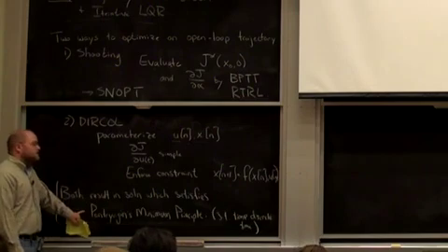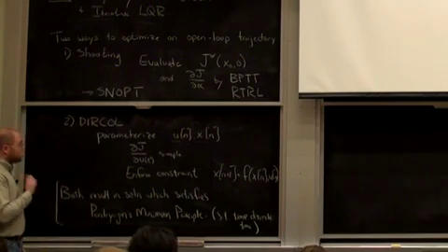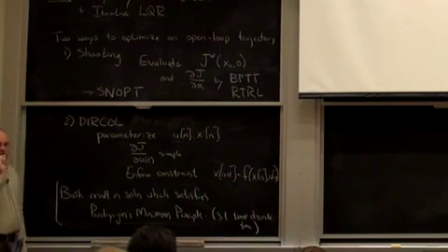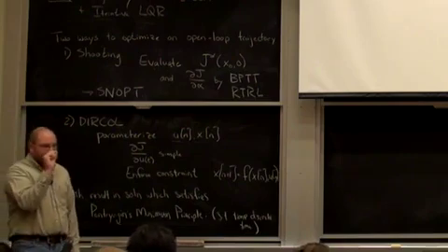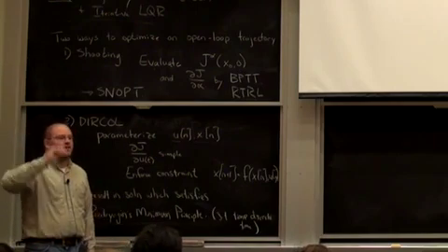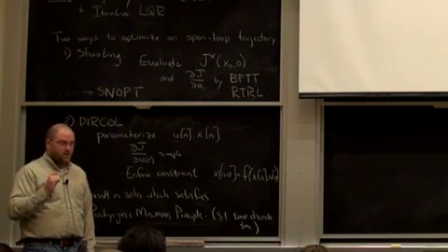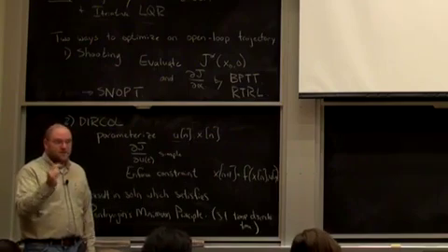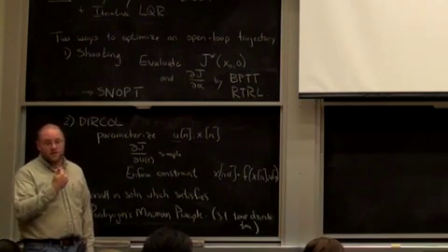satisfying Pontryagin's minimum principle, fine, but there's nothing in this process that says if I change my initial conditions by epsilon, I couldn't completely diverge when I execute that open loop trajectory, right? If I change my simulation time step by a little bit, I might diverge. If I have modeling errors, I might diverge.